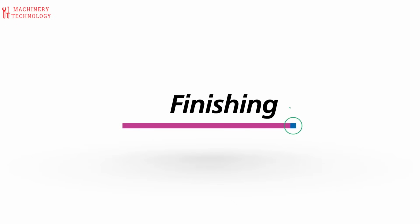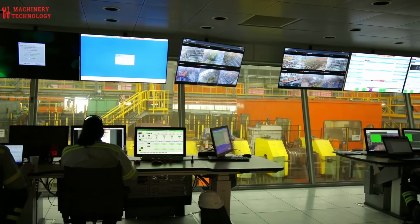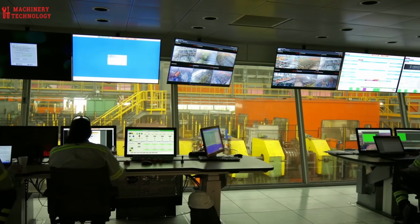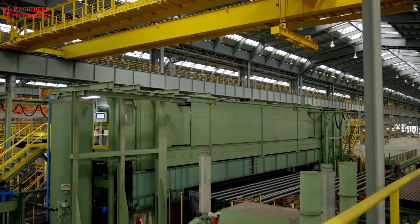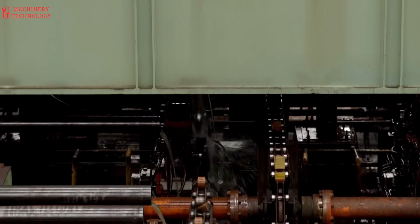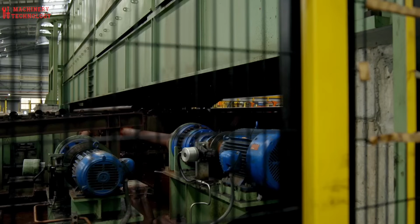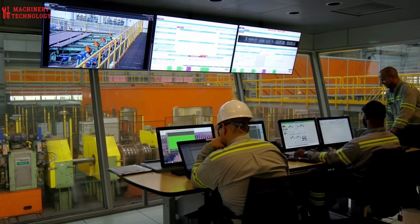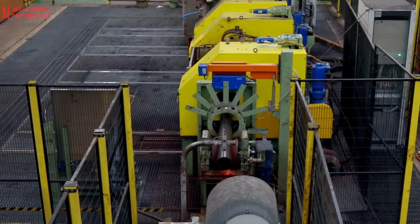Finally, here the automated line carries out rigorous testing and verification to ensure the steel pipes meet the quality level and specific customer requirements. Hydrostatic testing is first performed to ensure that it will meet the specified pressure requirements before being subjected to electromagnetic testing to detect internal and external defects. Ultrasonic testing then uses high-frequency sound energy to measure pipe wall thickness.